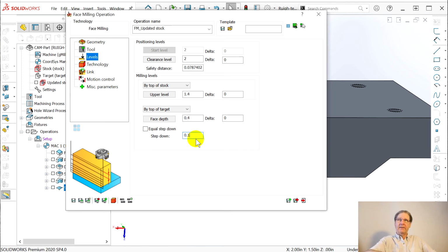I'd rather go down to a tenth because it's 4/10. Let's take four passes. They'll all be equal size, equal chip loads. Set the speed once with the controller, you can bump the feeds and speeds and spindle speeds up. And once it's doing good on one level, it's taking the exact same chips on all four levels. So that's why I changed this. I think it's ready to go.